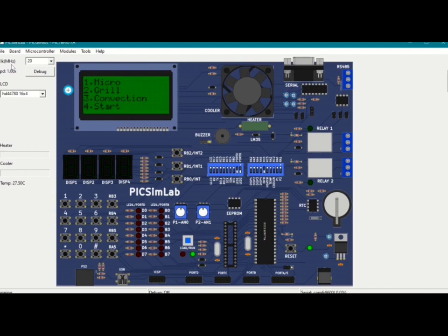To see the micro mode, we have to press the 1. Now I will press the 1. You can see the micro mode will be turned on. It takes the power 900 watts. Now we can set the time as per our wish, but the maximum time is 60. Now I am pressing the keys, tactile switches from the matrix keyboard. I am taking 30 seconds.